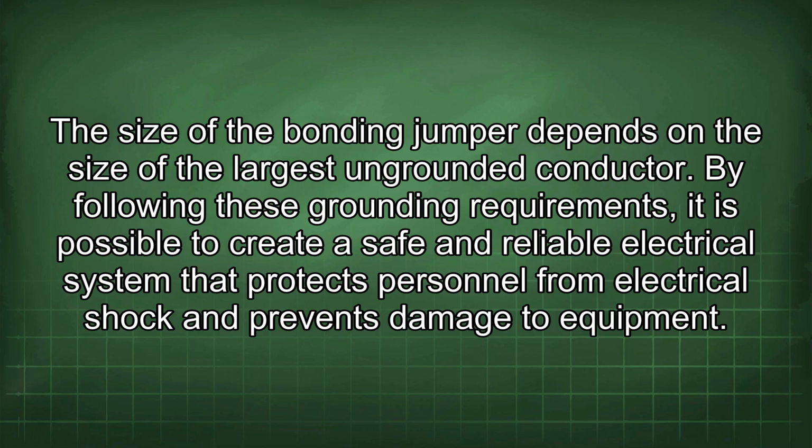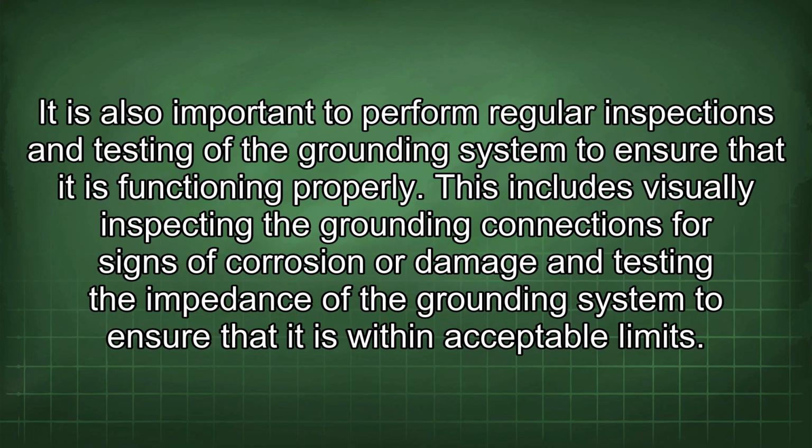By following these grounding requirements, it is possible to create a safe and reliable electrical system that protects personnel from electrical shock and prevents damage to equipment. It is also important to perform regular inspections and testing of the grounding system to ensure that it is functioning properly. This includes visually inspecting the grounding connections for signs of corrosion or damage and testing the impedance of the grounding system to ensure that it is within acceptable limits.